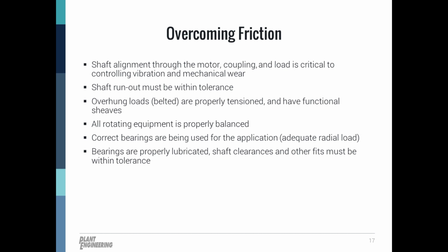If you're thinking about vertical motors in your facility, consider whether you have an axial force that may be upward or downward or balanced to determine if you need a thrust bearing on one end of the motor. And if that's the case, most commonly matched with a guide bearing on the other end.